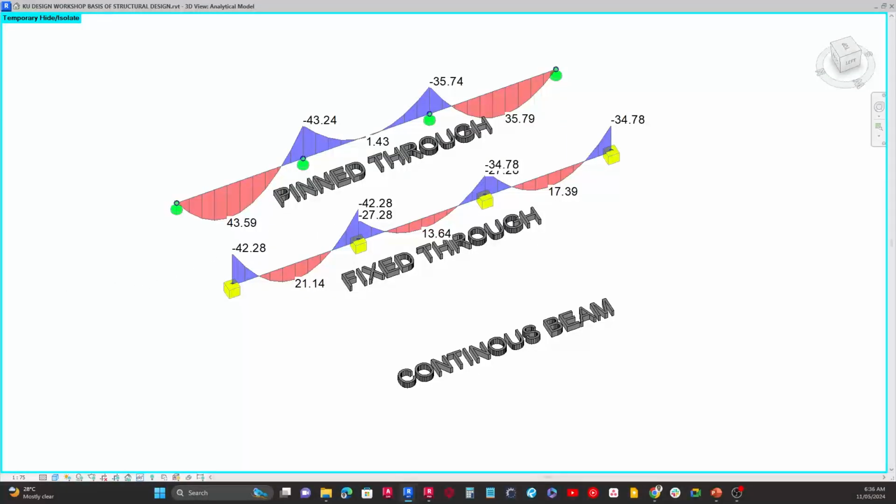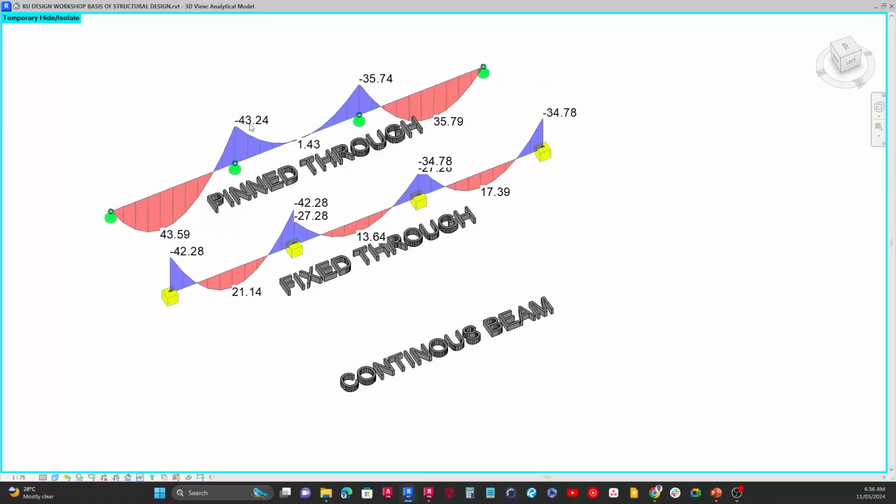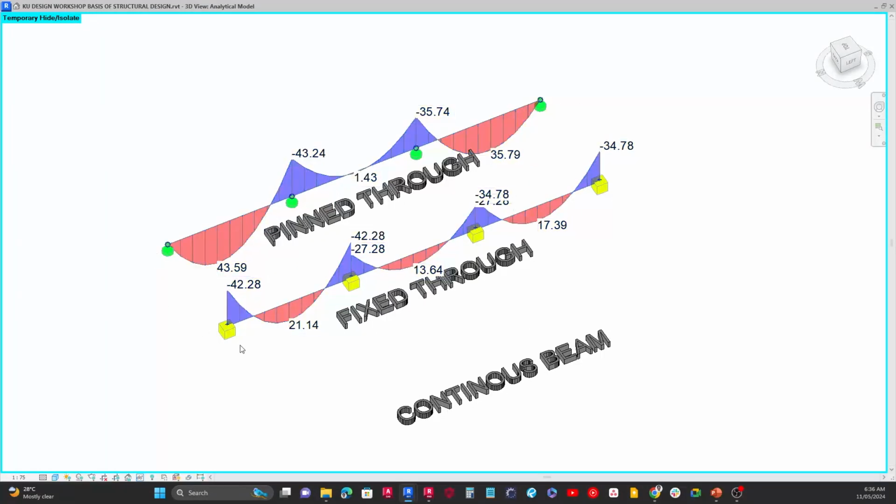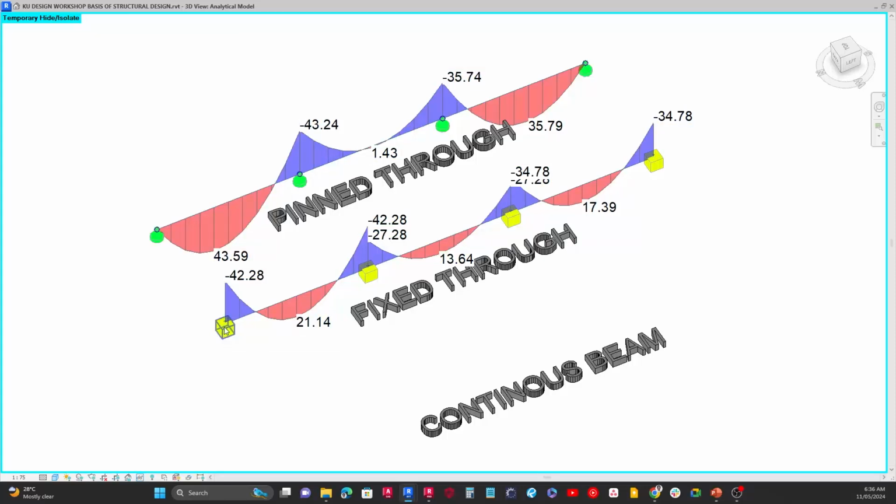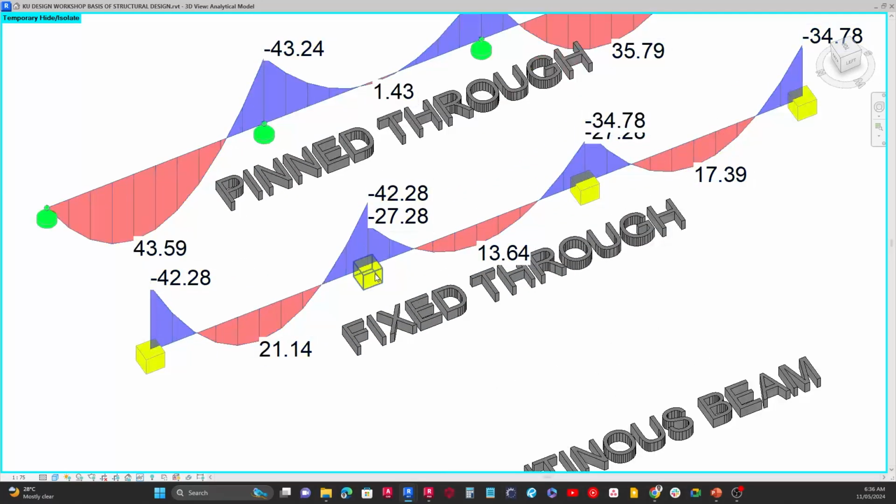Alright, good. So now we can see here that there's a difference between how these two structures are actually showing their representative analysis models. In the first case, just because we have a fixed support, there's moment generated here. But once it gets to in between two beams, a beam before the support, another beam here before the support, we can see that moment is generated here.